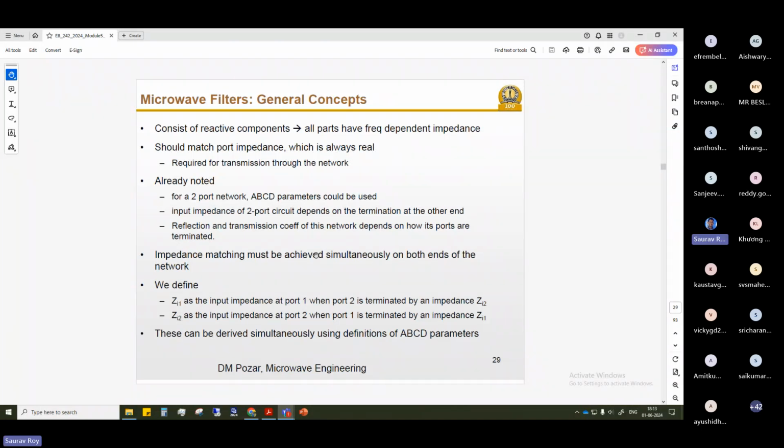So the main problem is that often in the previous courses, what you have done, you have designed with RLC, right? L, C and R. So here, if you design like that, you should know that in microstrip, in the microwave frequencies, they do not behave like only RLC. In high frequencies, there will be a lot of parasitic elements coming up. So it is no more like a normal circuit behavior.